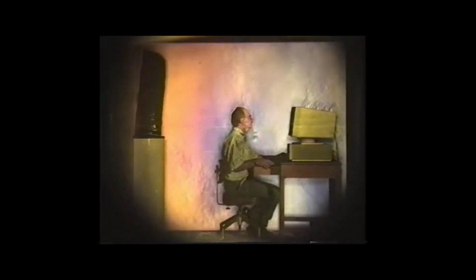Here we see thermal plumes rising from a person and a computer. This warm air is removed at the ceiling, while the air conditioner on the left emits cool air that falls to the floor in a scheme known as displacement ventilation. We can use the same approach to study ventilation in commercial kitchens, where the heat and fumes from a griddle are collected overhead by a ventilation hood.